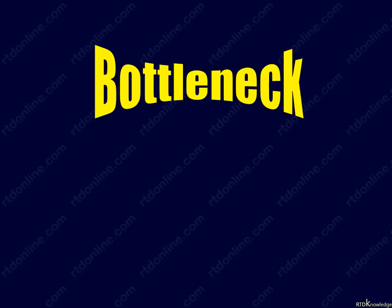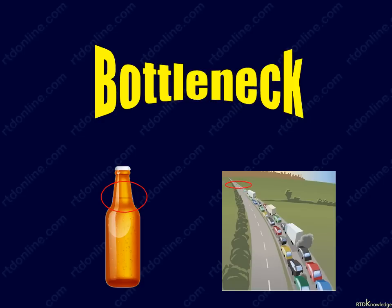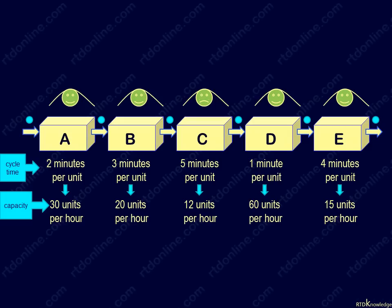Everybody is familiar with the real bottleneck, the narrowest part of the bottle that restricts the flow of liquid. Another familiar bottleneck is the narrowest section of a busy road that slows down traffic. Similarly, the workstation, wherever it is inside the process, with the longest cycle time or lowest capacity, is the bottleneck. Here we see that the slowest workstation C is the bottleneck. A process can have one or more bottlenecks if they have the same long cycle times.